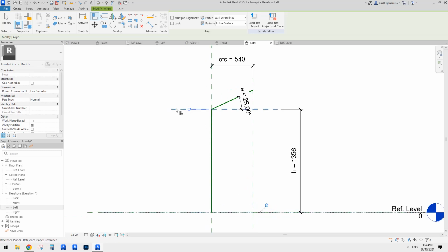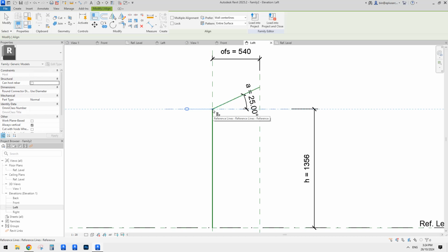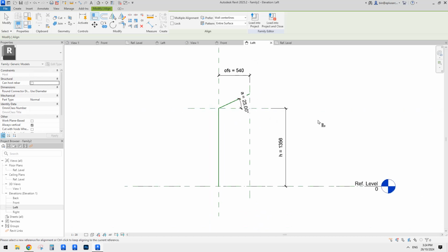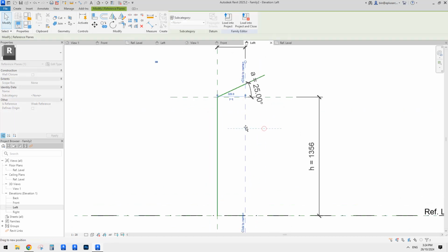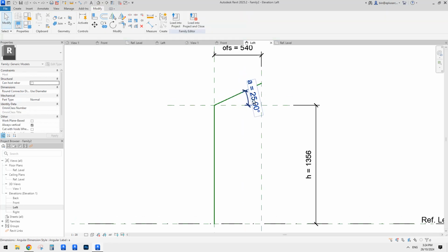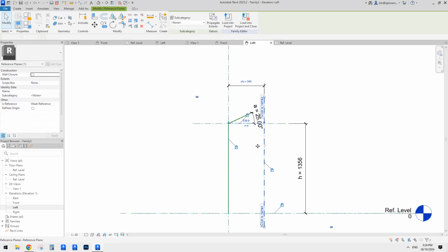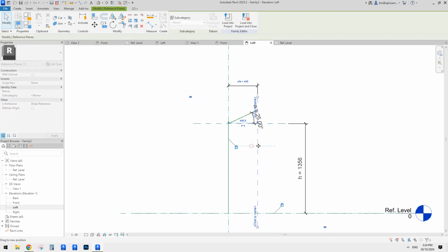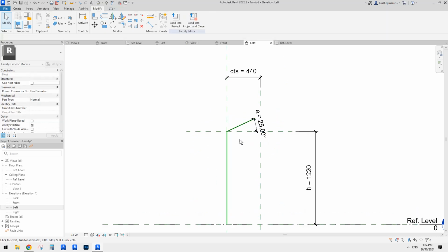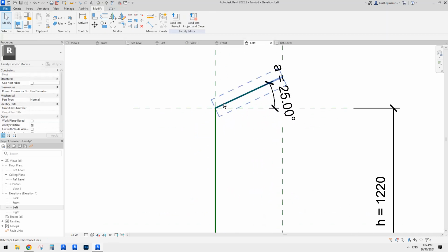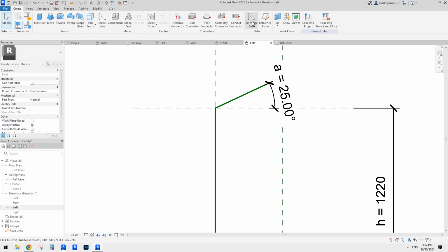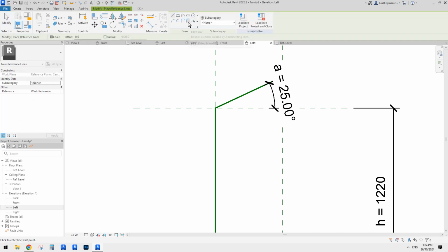See, there's another 0. So let's just tab, select, and that's all good, right? Now if I drag this one, it looks like we need to lock that end as well. AL, tab, and lock. Now it looks fine. So you can see we can adjust the offset and the height, but because we need an arc here, create a reference line.